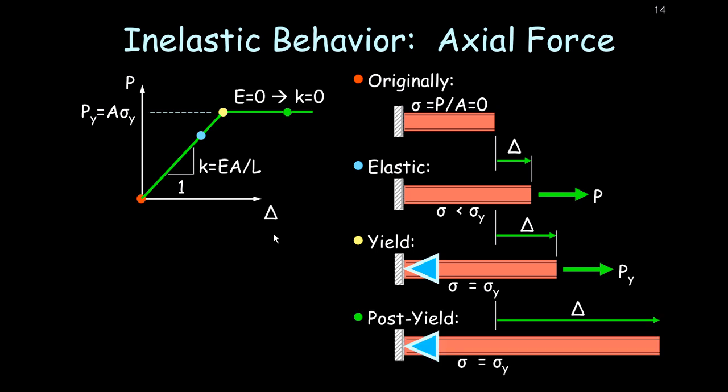Now, realizing that the material is fully yielded through the full depth of the member, none of the material in the member has any stiffness left. It's lost all its elastic stiffness. The E value, like I said, has been driven to 0. So if we try to put on any additional loads, what we would have is a significant amount of deflections. All right?